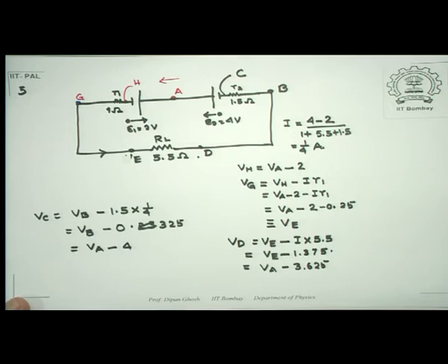So this essentially tells you how the potential drops are to be calculated. Now here I assumed a priori that current is in that direction. You don't really need to know the direction of current. Suppose you did not and you assume the opposite. So when you go opposite to the direction of current, then of course as you go through a resistance, we have seen that the potential will rise. So go exactly like this and come back to the same point.